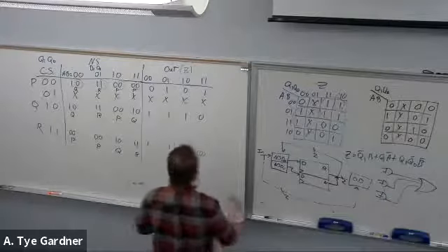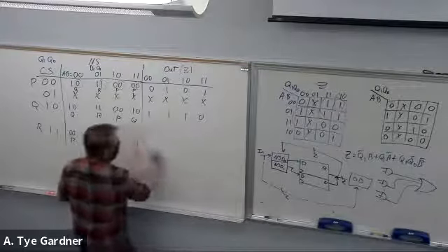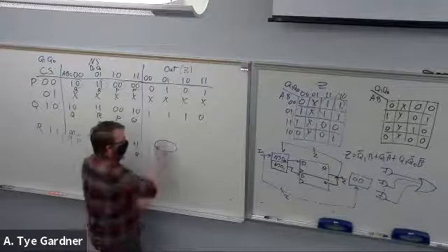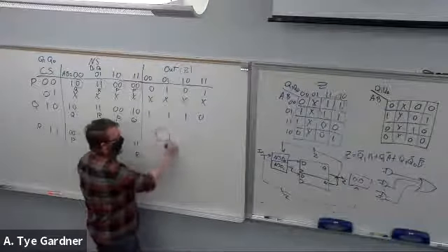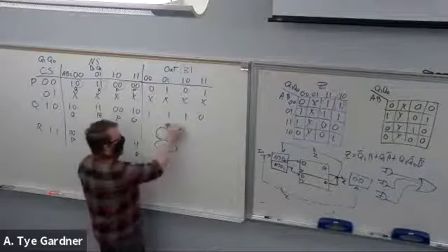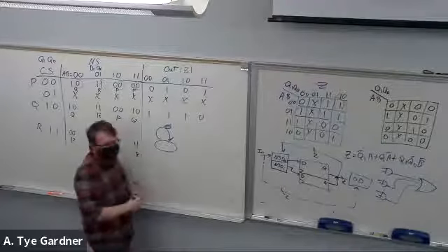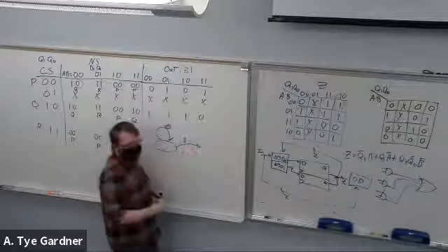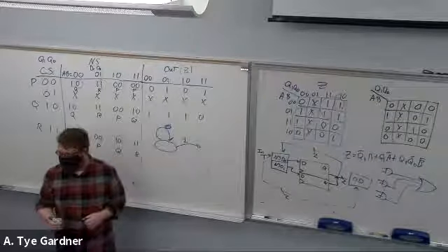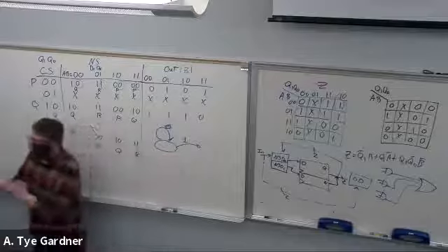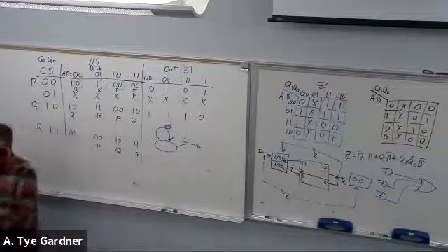And those are kind of interesting because you just start with the state because I've detected nothing, right? And I'm saying 101, so the first time that I see something, if it's a 0, I didn't start seeing that pattern, so we hang out. If I did see that pattern, let's move to the next state, right? Anyways, that's sequence detectors. We'll go make one of those pretty soon.